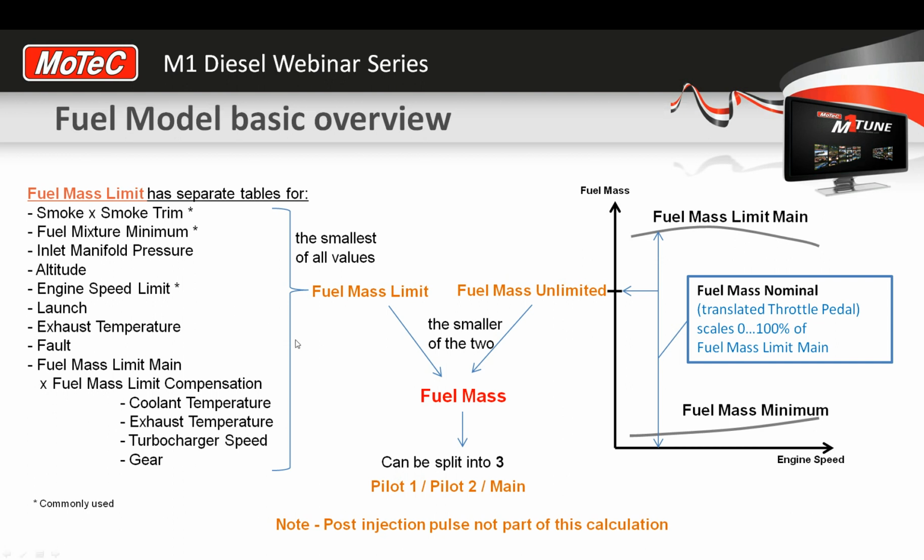Alright, so that's method 1 for dealing with smoke, or for trying to obtain a particular lambda value, if you like. Now, in racing terms, a fairly typical number to head for that's close to full power with minimum smoke, and I mean it's different for all engines, but a lambda value of around 1.2 would be a good starting point for any engine that you want to start tuning.